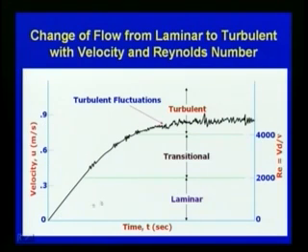We can see that this range is the laminar flow range. Then between Reynolds number 2000 to 4000, we have the transitional state, and then beyond 4000, you can see that the velocity is fluctuating with respect to the mean value. So, due to the fluctuations, the flow is turbulent, and you can see that the flow condition is like this.